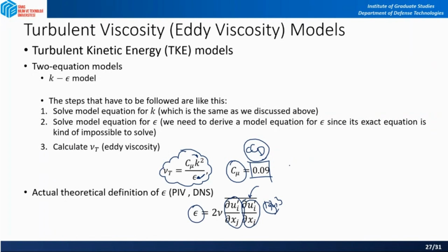Your camera has a specific number of pixels, megapixels. In a PIV experiment, you have a measurement grid. So you take data at every measurement grid. That measurement grid should be fine enough to resolve the smallest length scales in the flow so that you can take these gradients and find the spatial distributions. So it is very tough to measure these things.